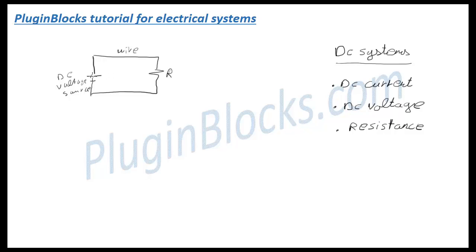But what is this really pushing and what is this really opposing? They are pushing and opposing charges. You can draw it here as a positive charge, as you can see here. So the DC voltage source is trying to push those charges and the resistance is trying to oppose them. This flow of charge is the current, and it has the symbol I, and it's equal to d by dt of the charge, q. d by dt is the rate of change of a charge.